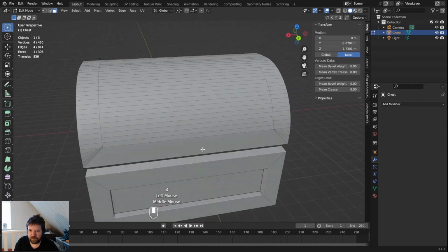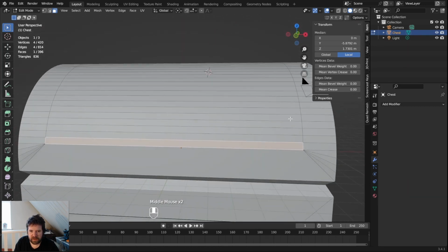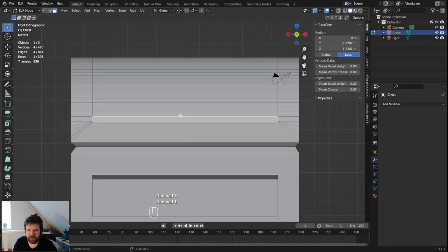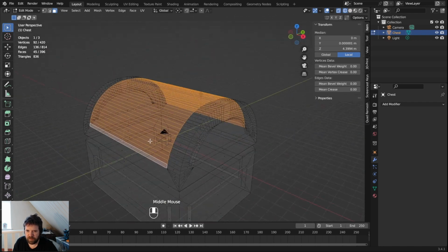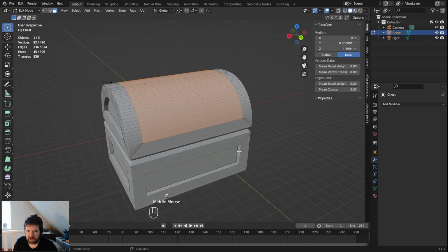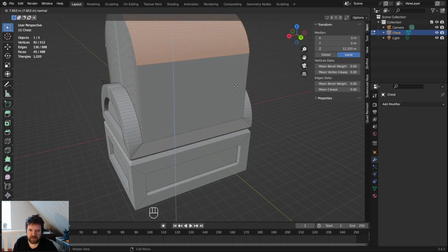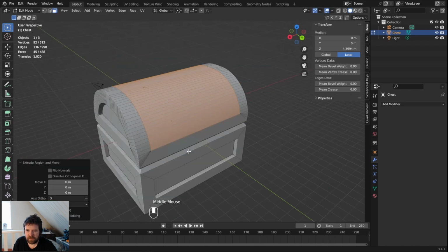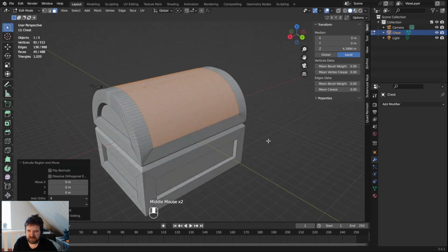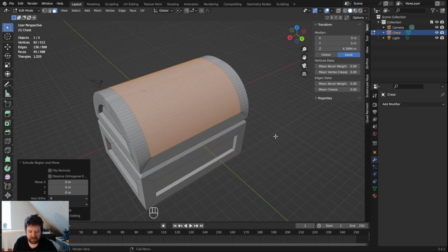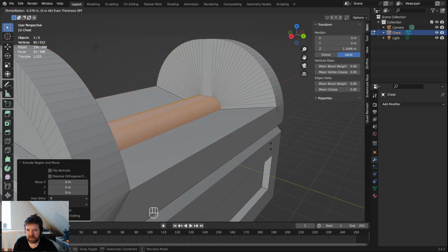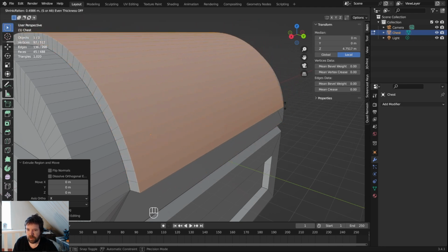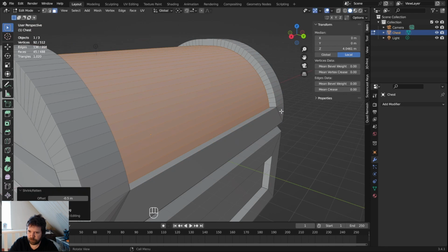So time for the last, and as the last time, we go into front view. We drag a little box around these in wireframe mode, so we catch both the front and back. We extrude. Look here, if we extrude, everything goes up because it takes the mean normal of all the faces. Right click to cancel it, so we extrude with a 0 distance and then shrink fatten. This is quite nice. So it moves along the normal, and we can minus 0.5.